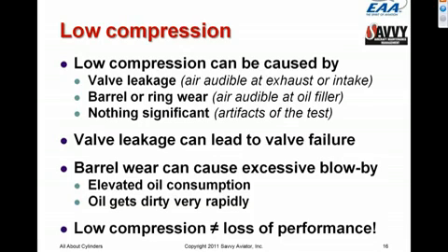We can tolerate a tremendous amount of wear on the barrel and the rings, but leakage past the valves, if it's actually happening during engine operation, can lead to valve failure in flight, which can ruin your whole day. So we're much more concerned about valve leakage than we are about leakage past the rings.